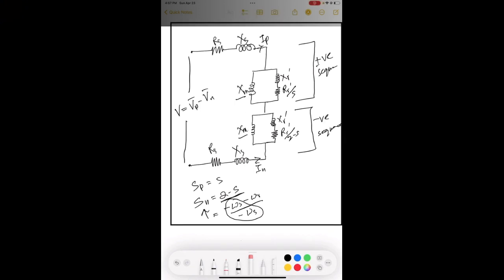Now, if I take the equivalent circuit diagram of a 3-lead connection, the positive and negative sequence parts are independent of each other, because the currents are different but the voltages are the same. Since they are independent, there is no restriction imposed on the negative sequence component by the positive sequence component of the equivalent circuit. Therefore, we can obtain a high braking torque.